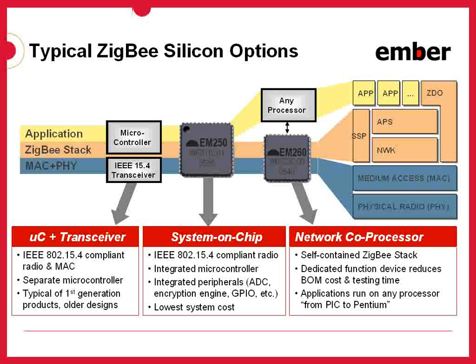The first variant, often seen in legacy implementations, is the RFIC model, RFIC being a dedicated RF transceiver component as opposed to a microcontroller or microprocessor. In this model, an 802.15.4 compliant RF transceiver manages the PHY and most of the MAC layer, but still relies on an externally connected microcontroller to manage the operation of the MAC and provide the implementation of the ZigBee networking stack itself.